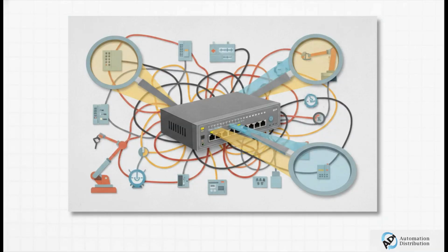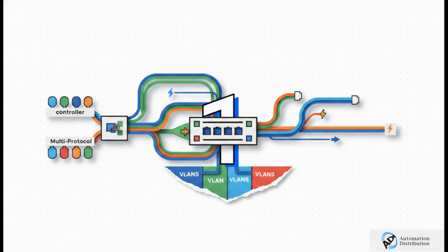So instead of that cheap, unmanaged brick, you really need purpose-built hardware, like a PROFINET-rated managed switch. These things handle stuff like LLDP topology discovery, which is absolutely required to keep chaos off your network. LLDP, or Link Layer Discovery Protocol, is a massive part of what makes PROFINET actually function correctly. If you use an unmanaged switch, it literally just drops those LLDP packets into a black hole, totally blinding your PLC to what's actually connected to it. Hardware like the Wago 852-1605 is built specifically to handle these PROFINET segments safely. Because if you get this right, it means absolutely everything.